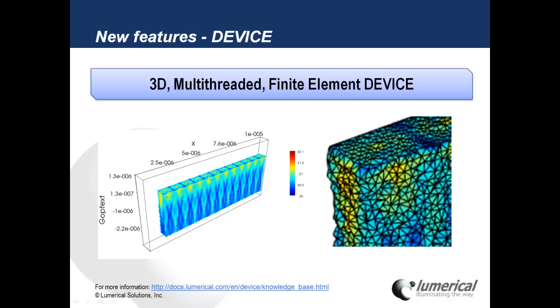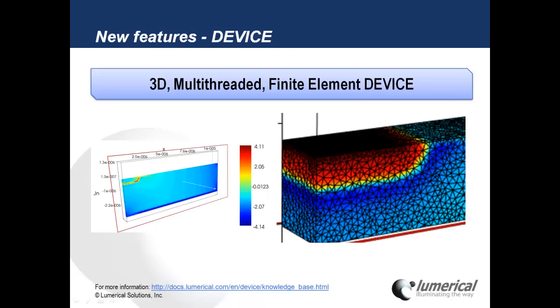So in terms of new features in this release, for Device, it's a major change. There's now a 3D multi-threaded finite element solver to complement the existing 2D finite element electrical solver that was there before. So this allows us to take very complex three-dimensional geometries and solve for the electrical properties. I'm going to show you an example in the application section on CMOS image sensors where this is extremely useful.